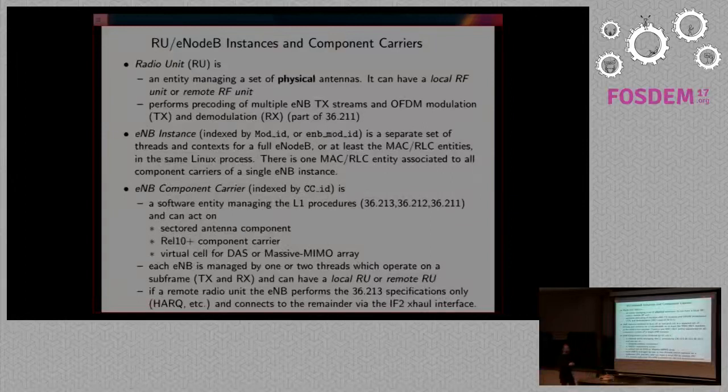There, implicitly, you're putting a fixed network between the two things. Now, what does it actually do? It performs two operations. It performs what we're calling pre-coding, and I'll explain what that is. Basically, that's the operation of taking several logical base stations and generating the signals on the antennas. Right? That's the notion of pre-coding. And it also does OFDM modulation.